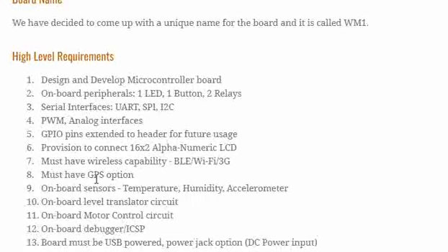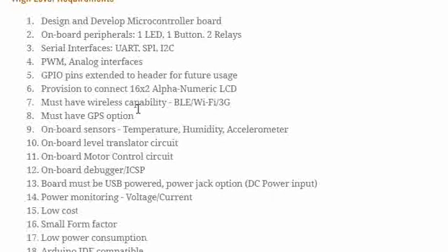And then they're asking for PWM and analog interfaces to be included, all the GPIO pins to be extended to a header for future usage, and they want to have a provision to connect a 16x2 alphanumeric LCD, which is a very basic LCD used for embedded systems. And it should have wireless capability because this is a microcontroller based wireless evaluation kit, right? So you have a requirement for BLE, Wi-Fi, 3G,